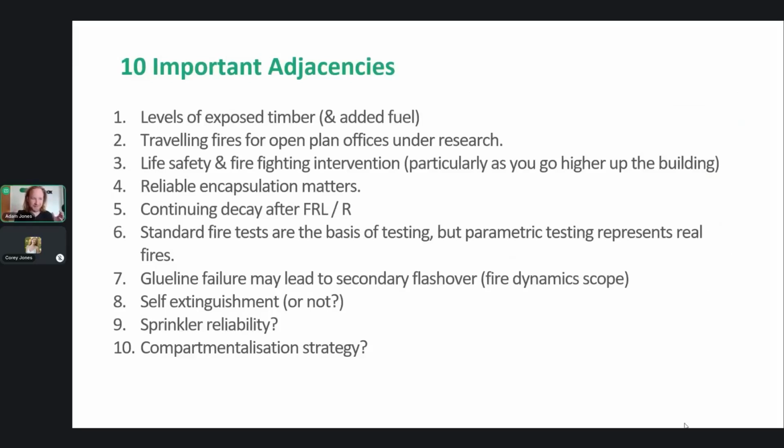All right, so before we get into it, I think it's always good to start at the very high level, some of the topics and the breadth of topics that come up. And most of these, we're not addressing in detail today. When it comes to structural fire design of timber buildings, you have to think about the levels of exposed timber and added fuel. Do you have multiple surfaces exposed onto each other, and how does that add fuel to the fire? Travelling fires for open plan offices is under research, and sometimes the testing doesn't cover the cases of open plan offices. There's consideration to life safety and firefighting intervention strategies.